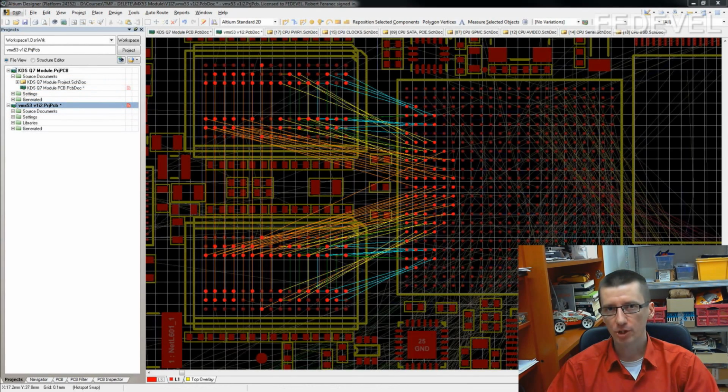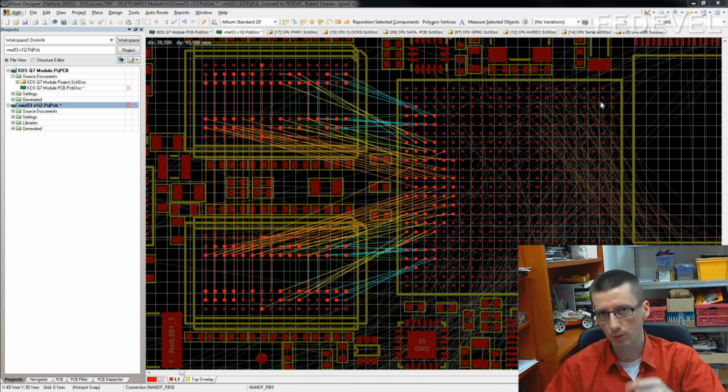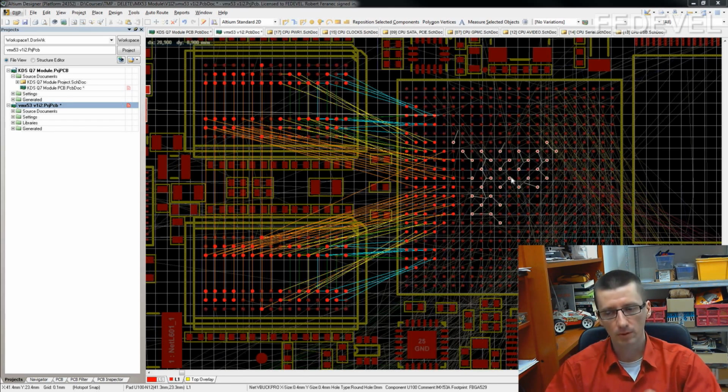The next step is to finish the area under the processor or FPGA. We already have there some preliminary placement, but once we start putting their vias, we need to move and shift the components around. And what do you think, where do we start? Do we start in this corner? Or where do you normally start? What is the best way to start? Is it the corner? I normally start in the middle because then I can go with the components from the middle to the edges.